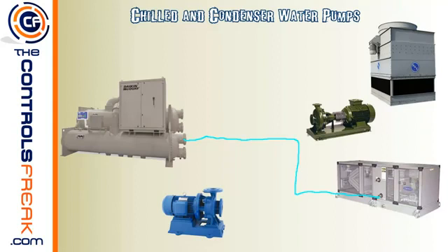And the reason why they do that, and it'll help you identify what piping is what, is that way when you fill this coil with water, you always want to have the outlet of the water coming out the top of the coil. And the reason why is you want this to fill up with water before trying to pull it out.